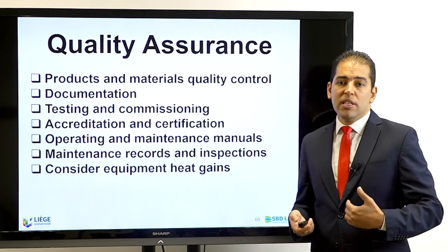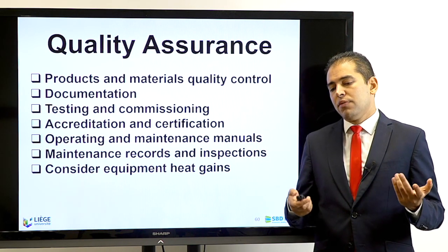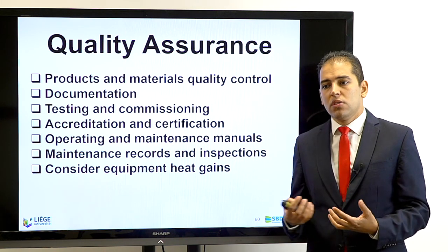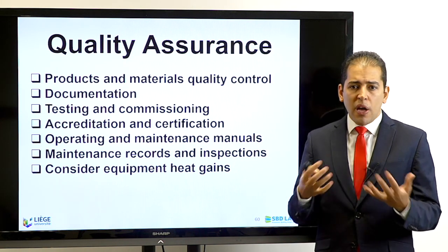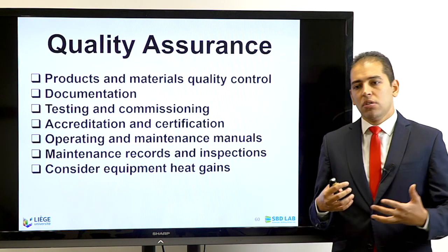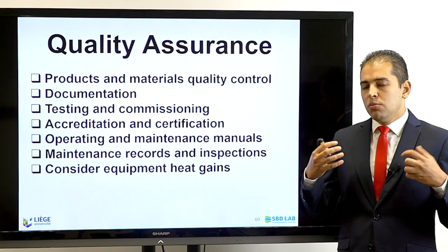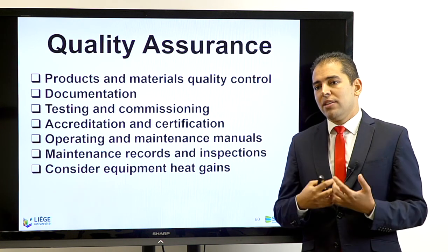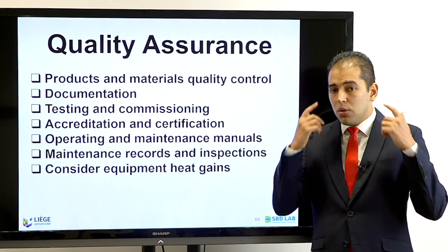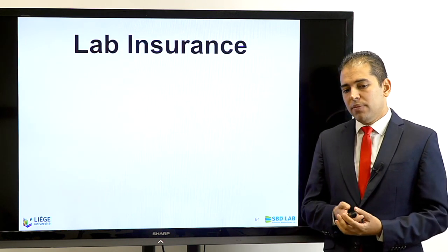Consider the equipment heat gains, very important, because today in many buildings we have too much heat and then we have a climate that is changing, so it's getting hotter and hotter, and in many labs there are fires and there are high heating loads, demand for cooling. Later on we have ad hoc solutions to integrate cooling or introduce a ventilation system. So you must make sure beforehand when you're designing the lab what kind of equipment you have and what kind of heat they will generate, what kind of noise they will generate, and in advance prepare the lab for that.